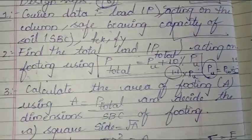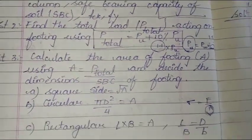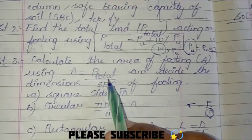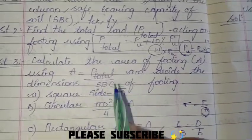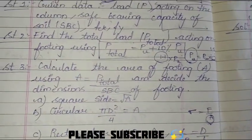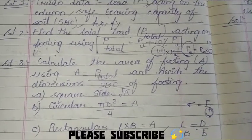That is nothing but the stress. So from this formula we can write area is equal to force by stress, that is P total divided by SPC, the safe bearing capacity of the soil, and decide the dimensions of the footing. So first of all, we are calculating the area of the footing.